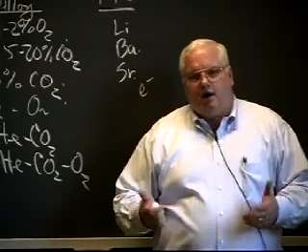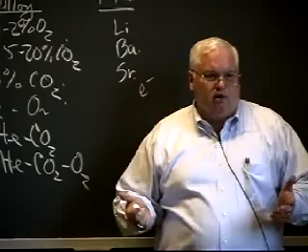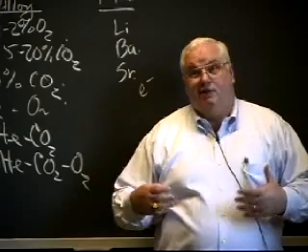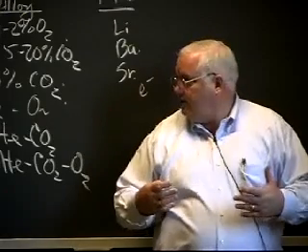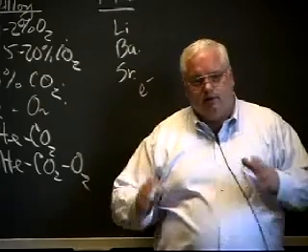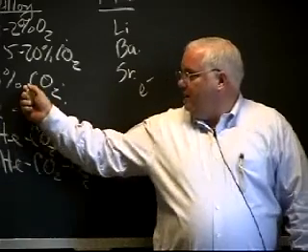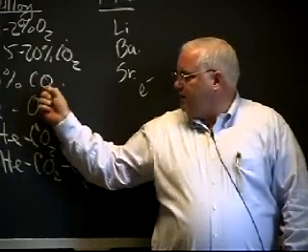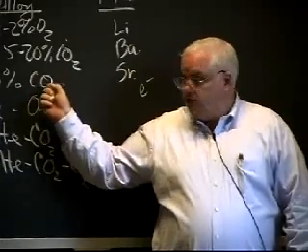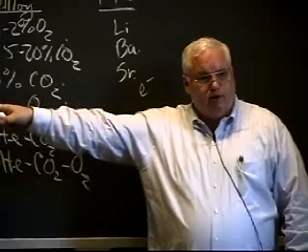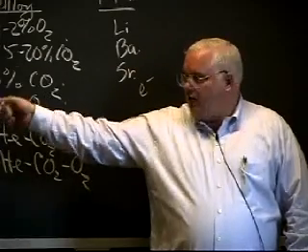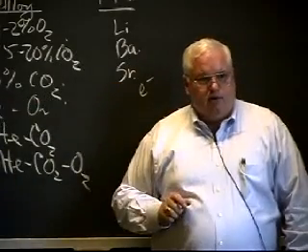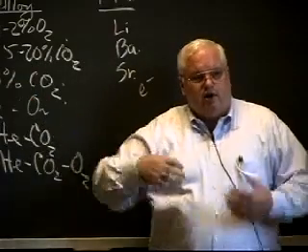If you're in a non-cosmetic situation, it's no big deal. If you're in a cosmetic situation, like an automobile, you have to come along and grind it, and there's all kinds of problems with that. In general, there is an oxidation that goes on with 100% CO2 because 50% of your atmosphere is going to be oxygen. You can tolerate 5% oxygen in your atmosphere, but at 50%, you're going to start to oxidize your steel.